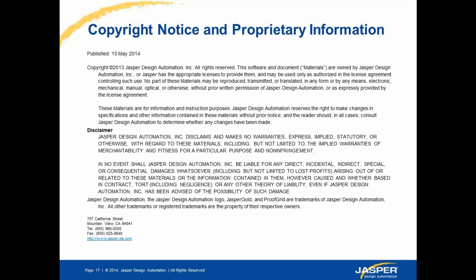Okay, but that's presuming you've done a complete verification. No, because a bounded proof is far more valuable than hundreds of simulations you have done. So using the coverage metric that you have extracted from the bounded proof, you can actually sign off on the effort you have done.